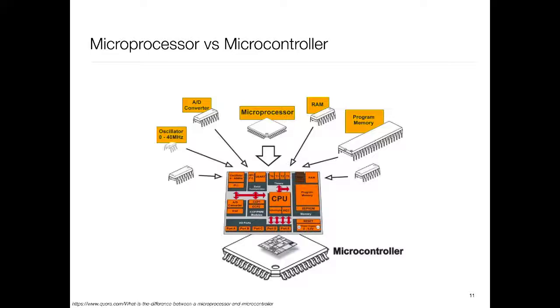Whereas in microcontrollers, all you would have at the boundary of the chip would be general purpose I/O and serial lines and things like that. There is no address data bus. It's too expensive, because the moment you have an address data bus, you're talking about lots of pins, a huge package, and the cost becomes too high. So the goal here is to take that part which would normally require a very large number of I/O pins, and put it all on a single die.